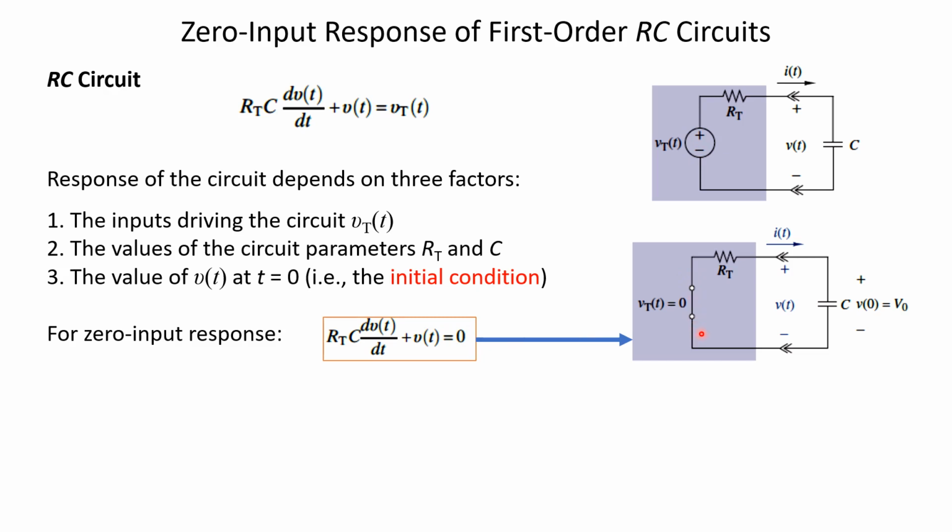You also know that if we eliminate a current source, we leave it open in order to make the current 0. So in order to set the voltage to 0, we remove the voltage source and then we short circuit this to ensure that the voltage across these two points is 0. Now how may current be flowing in it? There is no voltage source.